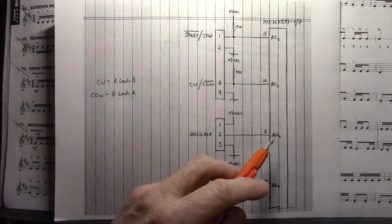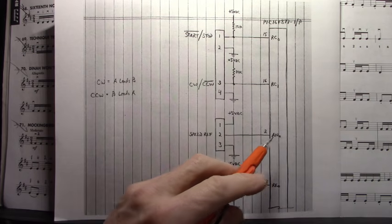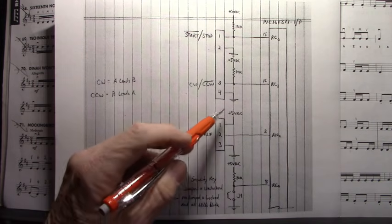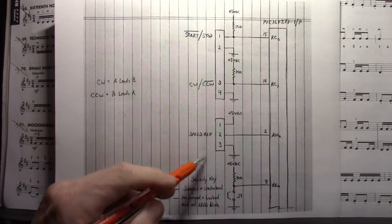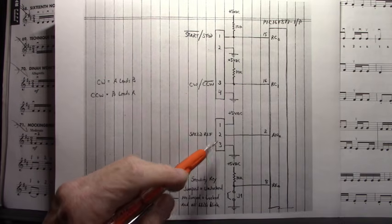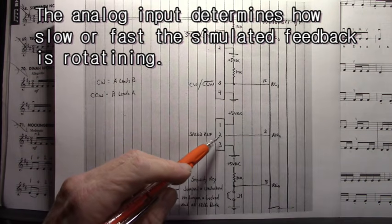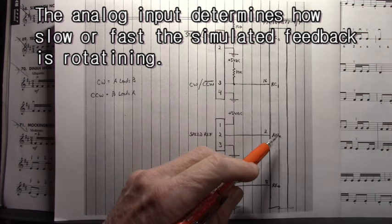Here we have an analog input, bit 0, and I have a potentiometer from the wings of the potentiometer connected to pin 1 of this connector, the ground connected to the other wing of the potentiometer, and the wiper connected to pin 2, and that goes to analog bit 0.